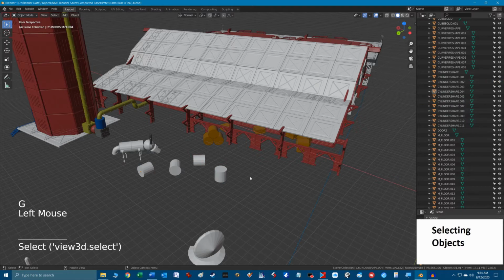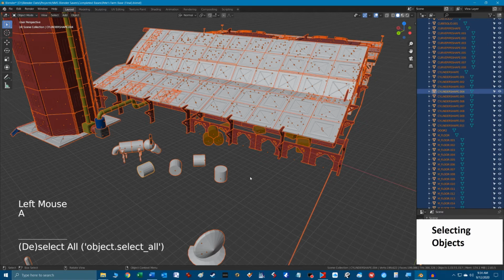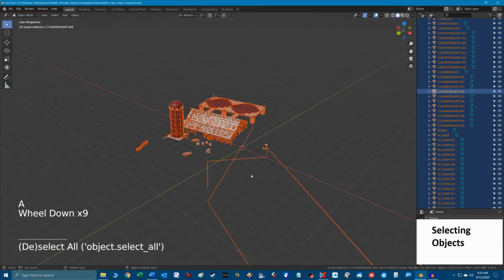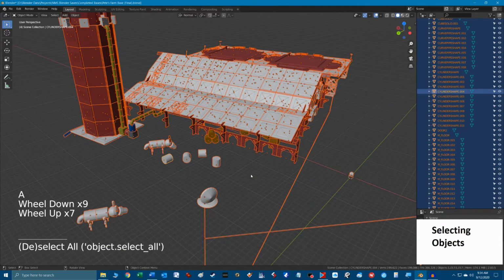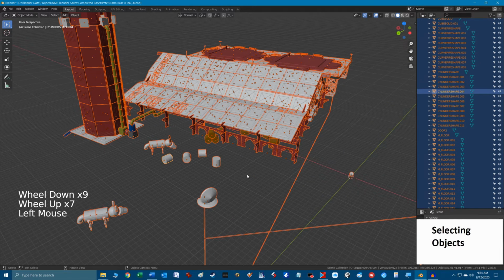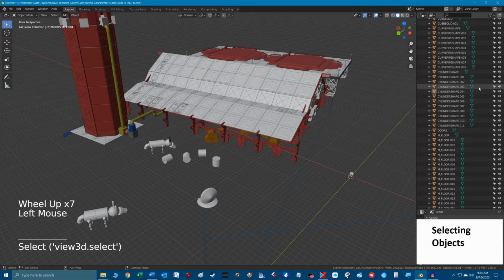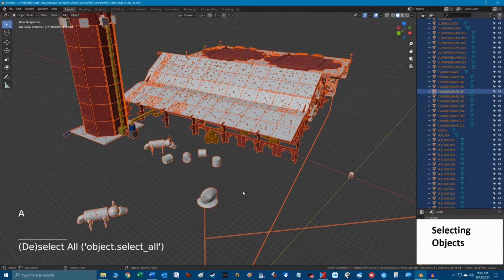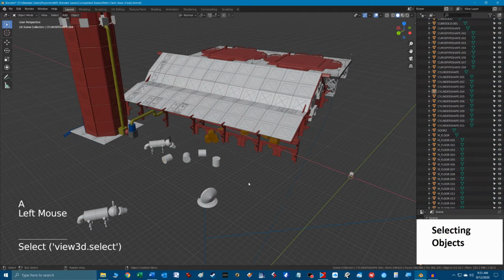If you want to select all objects on your base, with the cursor in the main window, hit the A key. This will select everything that is not hidden previously with the H key or made invisible in the Scene Object list at the top right. To deselect all selected objects, just click anywhere on a blank space or quickly double tap the A key.